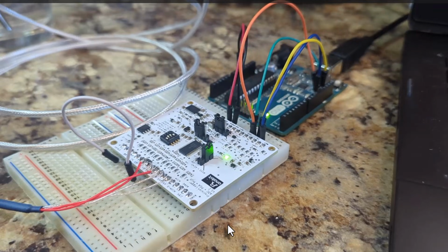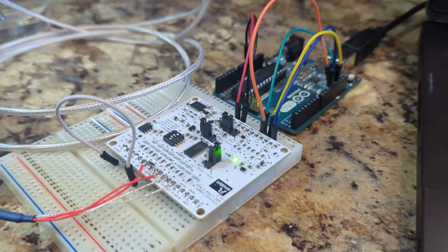Okay, here's a zoomed in picture of our precision logger board. We have our 4-wire RTD set up here. This outer wire is where the current source goes into, and this is where the current source comes out of. I don't know if you can see it, but I have my precision 1K ohm resistor soldered across these two leads. And this white wire serves as the return path to ground for the current source. So for our first configuration, the ratiometric configuration, let's see what we get with our measurement.